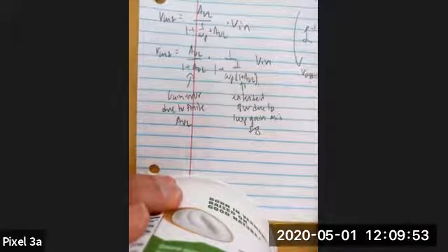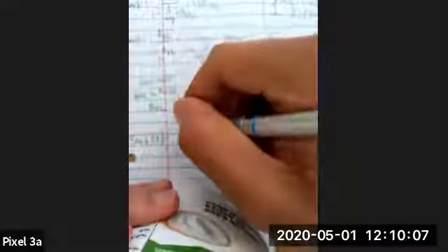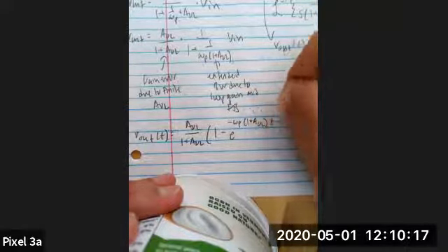And so if we use similar tricks to put this back into the time domain, we'll see that V out as a function of time is now going to be A open loop over 1 plus A open loop times 1 minus e to the negative omega p times 1 plus A open loop times t.